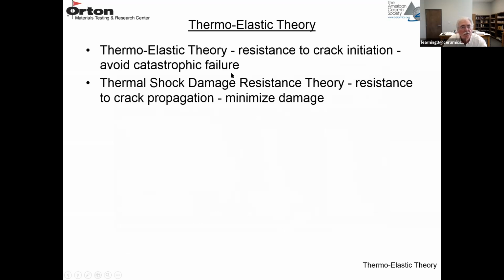And there's 2 approaches to designing a ceramic or a refractory to resist thermal shock. The first is thermoelastic theory. And that's an approach to design a material that totally resists any crack initiation. You don't want any cracks to initiate or grow, and you completely avoid failure, any type of catastrophic failure.